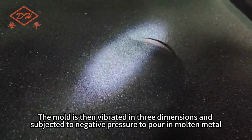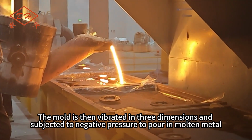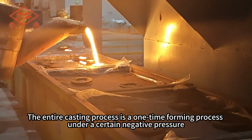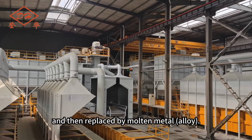The mold is then vibrated in 3 dimensions and subjected to negative pressure to pour in molten metal, forming the casting. The entire casting process is a one-time forming process under a certain negative pressure, where the foam model is heated and decomposed, and then replaced by molten metal alloy.